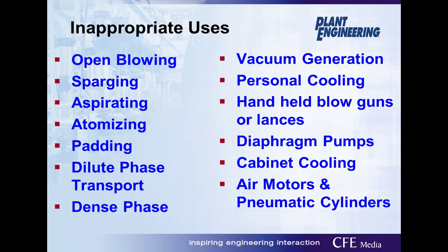So what are some of the inappropriate uses? This is the list that we have from Compressed Air Challenge. I'm not going to go into details on each one, but really, anytime you're using air to blow, to mix, to atomize, to transport materials, to create a vacuum.